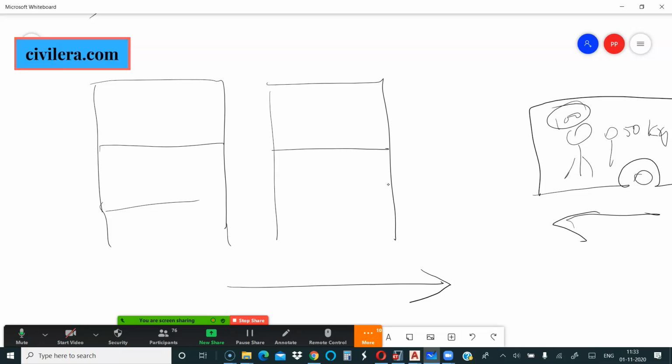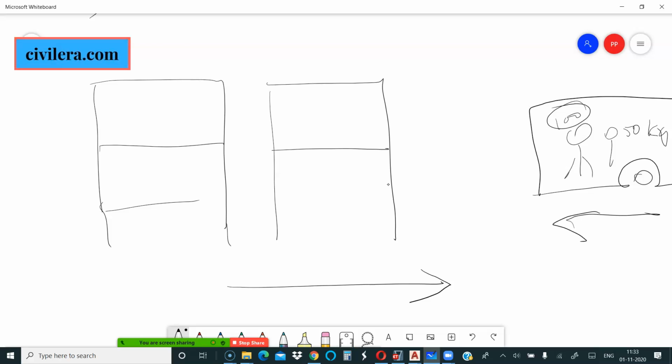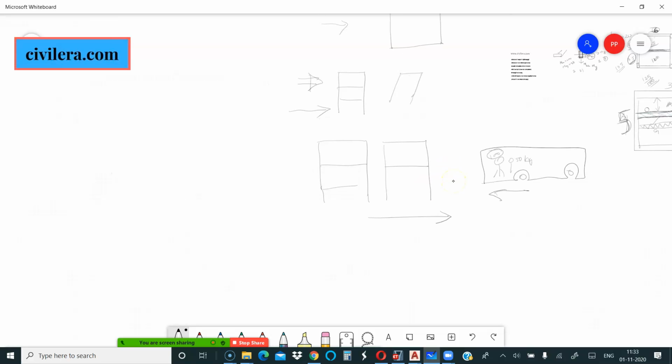So always coordinate with your architect. If there are uncertain things like the thickness of your tiles or stair tiles, and they have not been able to freeze that, try your best to freeze it, because all these are going to help you fine tune and reduce your seismic weight and thereby economize your structure. Simply compromising is not the solution for reducing structural cost.